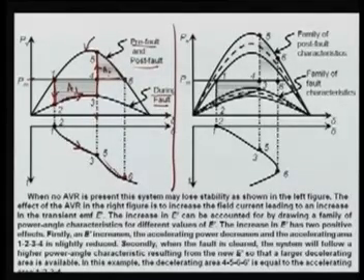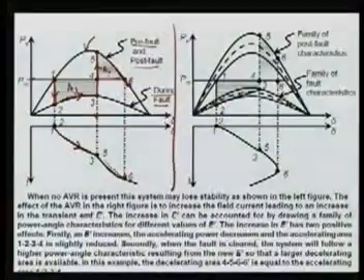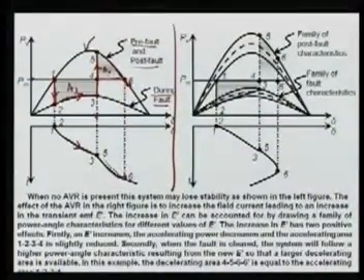So it will keep on moving, and once it crosses 0.6, what happens after crossing? Again this machine is going to accelerate. This delta was increasing, it should come back, but it keeps on moving and goes beyond control, and your machine becomes unstable. Now let us see the impact here on your right hand side.